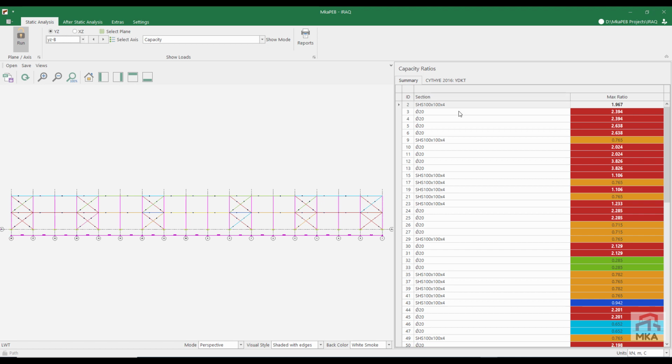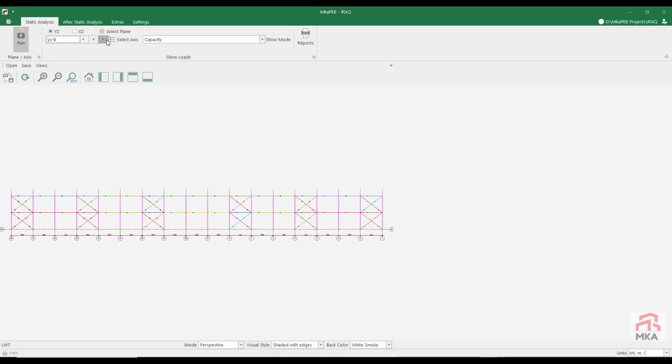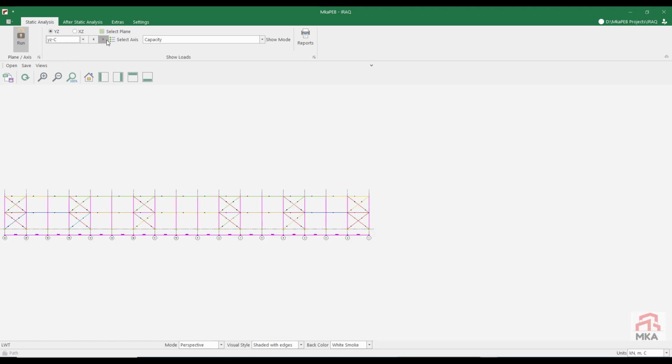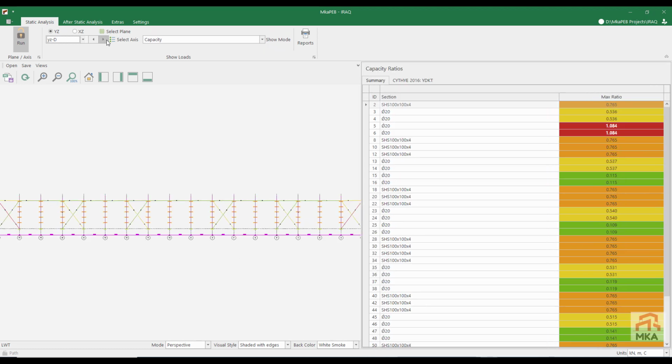Because the sections of these elements need to change according to the wind coming from the front shield, our side bracings were not enough as we expected. We can use CHS profiles or large rods on this axis. But I will prefer to use a CHS profile on this axis. Likewise, on the right axis, instead of the 20 rod.